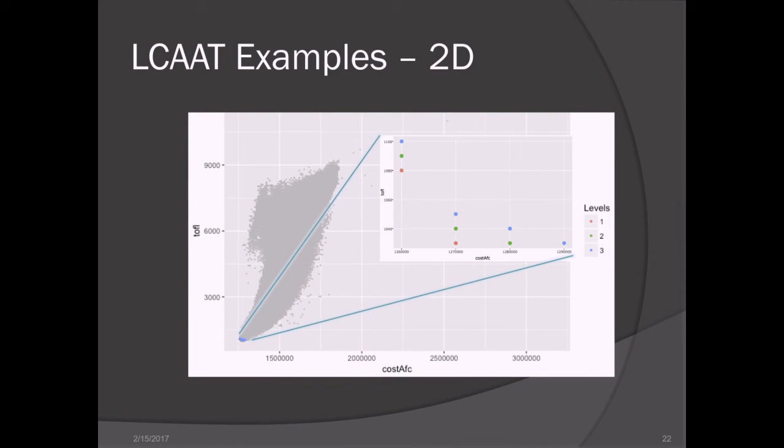And here's another example where I've done 3 different levels of Pareto points. What we've been looking at are the level 1 Pareto front points. What can happen, though, is that you can compute the level 1 Pareto front points, remove those from your design set, and then compute another Pareto front. Those become your level 2 Pareto front points.